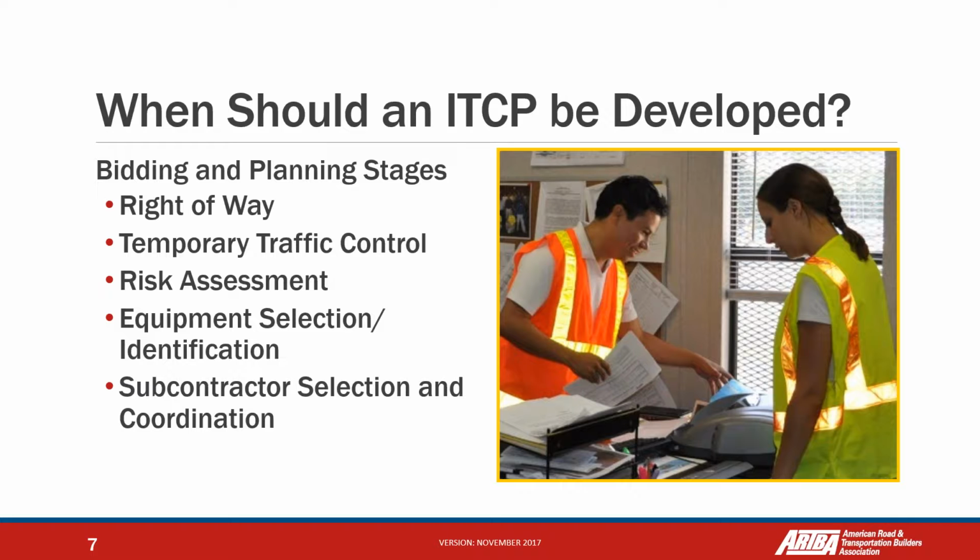We need to call 811 to know about underburied utilities in this area. We are going to have confined spaces here, fall hazards there, cave-ins here, traffic there, all the hazards. We have to evaluate all the hazards. And then we are going to plan what we are going to do to neutralize the hazards.